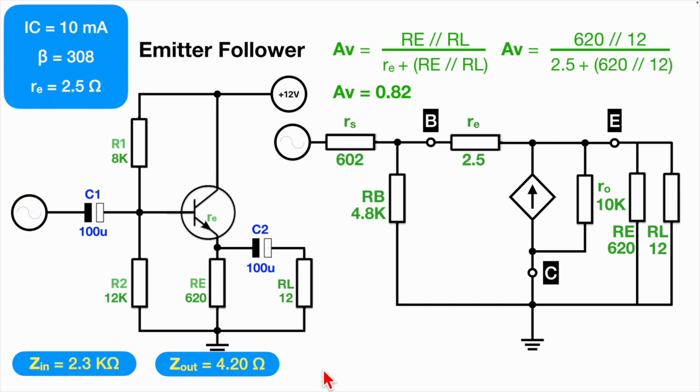We're losing a bit of voltage through this amplifier, but we're gaining a truckload of current. That's why it's such a useful buffer circuit, because it preserves most of the voltage gain of the previous circuit, but really beefs up the current that enables us to drive a lower impedance load.